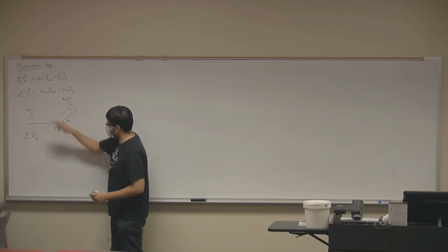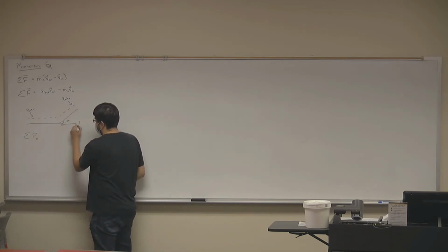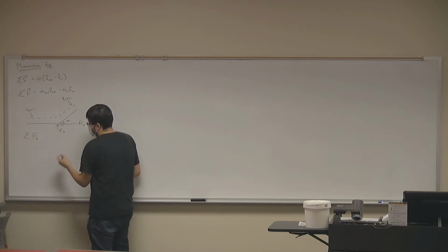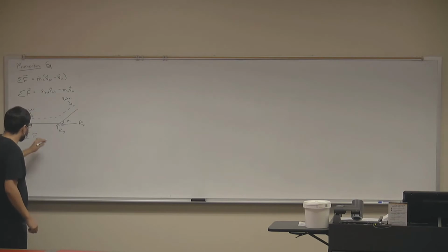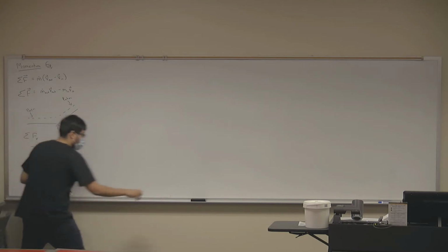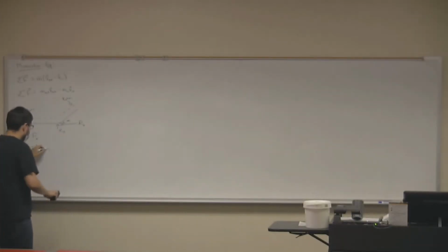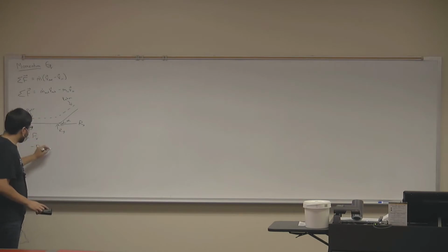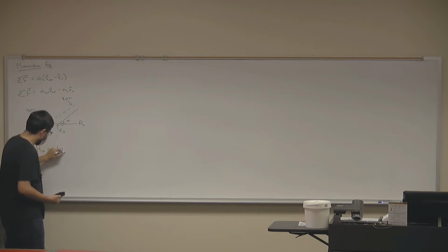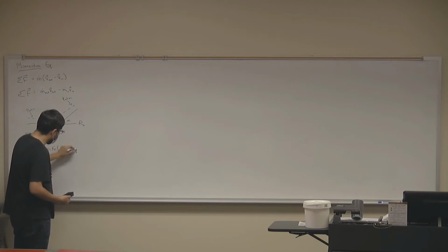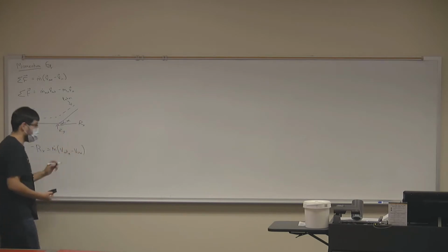of this system where you have your deflector, and the deflector is held by a horizontal and a vertical reaction force, then we said that the sum of forces in the x direction should be equal to negative my reaction force, negative because it's just pointing to the opposite direction of flow, and that from the momentum equation is equal to mass flux out, V out minus mass flux in, V in. But of course, we're only looking at the x component of those velocity components.